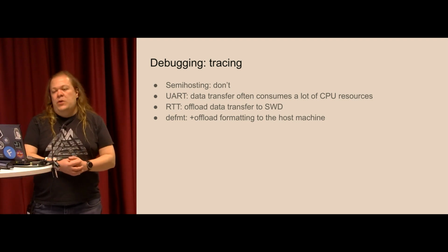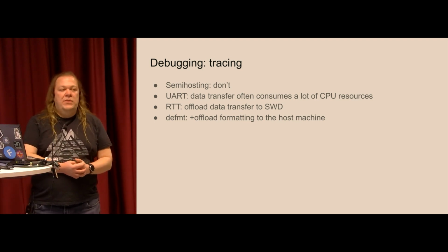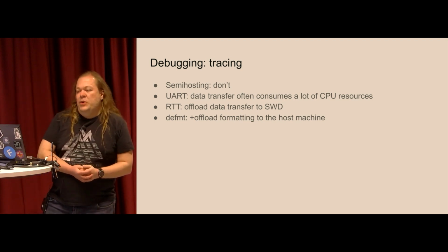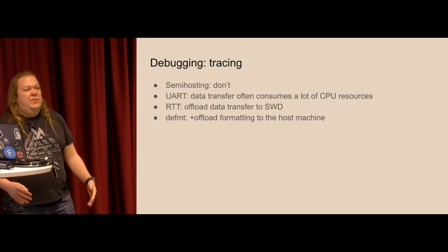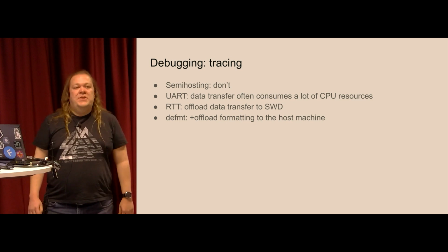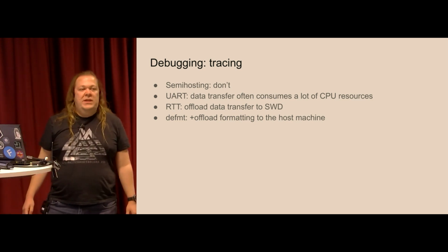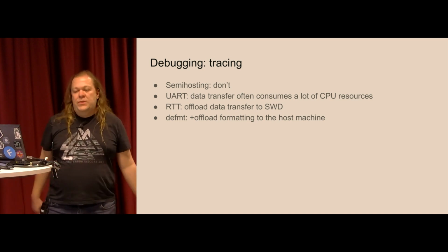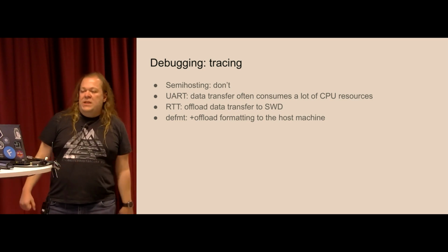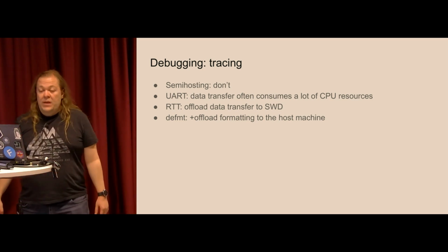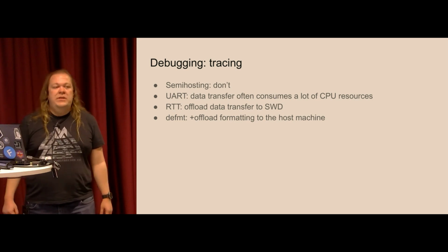And this is a big problem because often drivers are quite simple and a lot of CPU power is just consumed to send bytes towards UART. Unless you have DMA or something fancy like on NRF52, which can send something transparently out of the UART, this will not work. And then we finally have RTT.